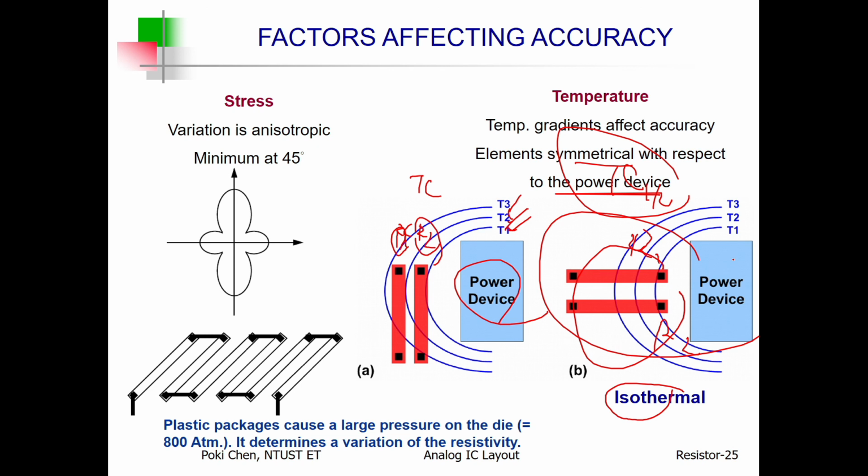We need not only to face temperature variation, voltage variation, but also stress variation. I mentioned already. Because the silicon lattice is anisotropic, which means it is not isotropic.